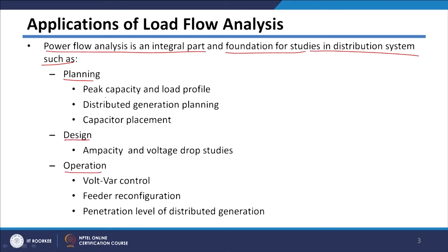In planning, studies like peak capacity planning or load profile planning use load flow analysis, along with distributed generation planning and capacitor placement. Related to design studies, there is calculation of ampacity requirements and voltage drop requirements in a distribution system.